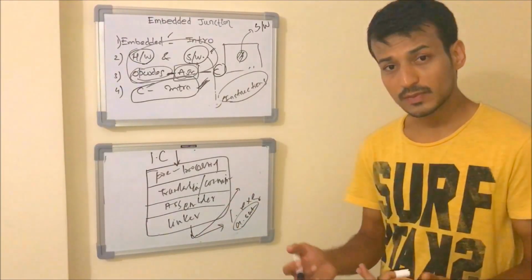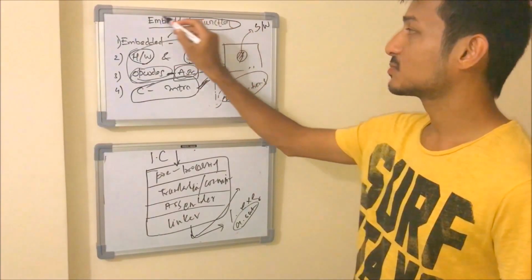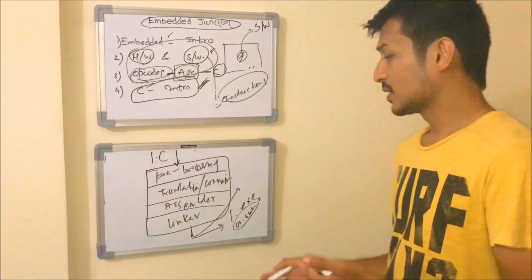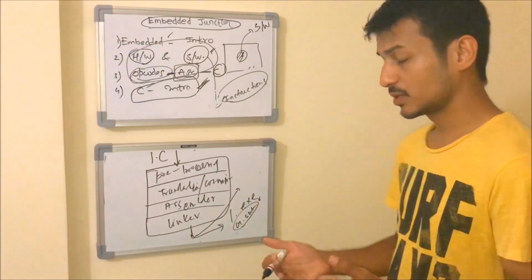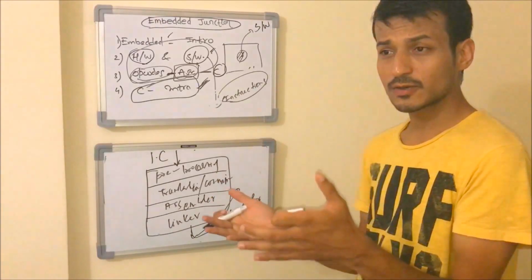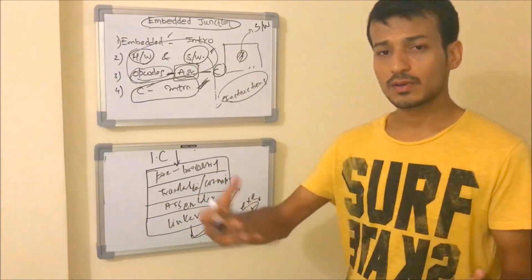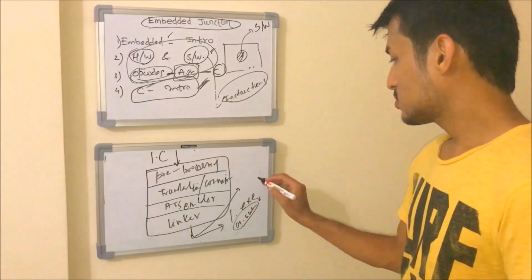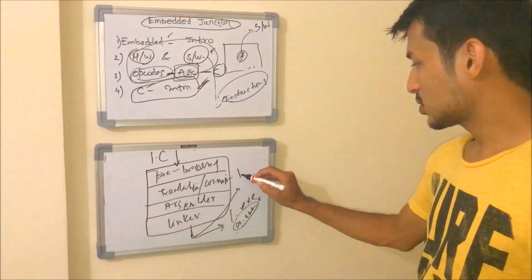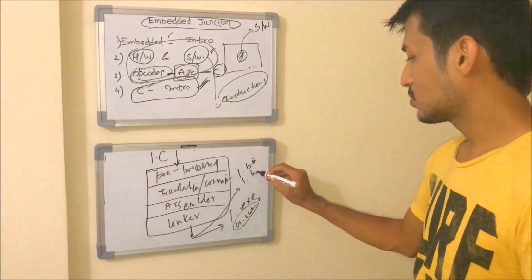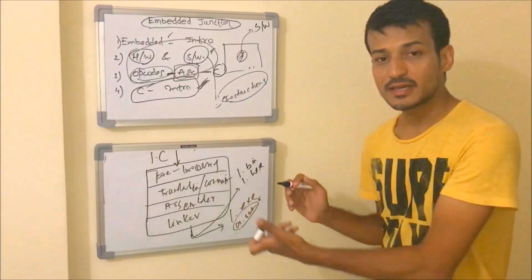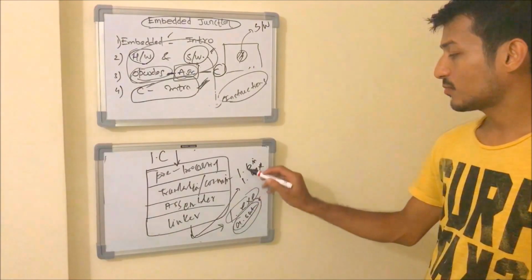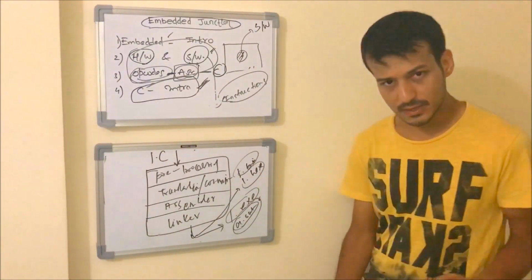If it's a cross-platform development, like for embedded systems, we are developing applications which are cross-platform compilable, and the development process is known as cross-platform development because we compile the code on a Windows machine and we download the code onto a target hardware which is of some other manufacturer. So the cross-platform output is the binary file, the hex file, which has nothing but the instruction set.